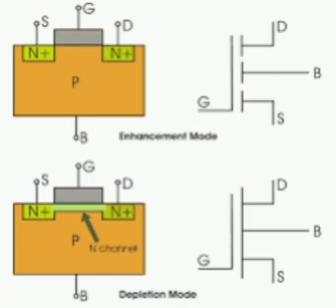Power dissipation in a transistor is given by PT equal to modulus of IC into modulus of VCE, where IC is collector current and VCE means collector to emitter voltage. Power dissipation in saturation and cutoff region is almost zero. Power dissipation is maximum in the active region.